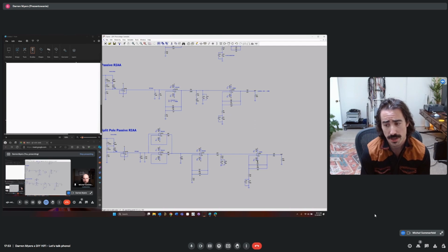And so, some people use batteries in these designs. Some use very traditional linear power supplies, like using an LM317 and LM337 to create your rail voltages. That could be a good option that is simple to design into this. That is almost like taking a solution off of the data sheets and making a linear power supply with it.